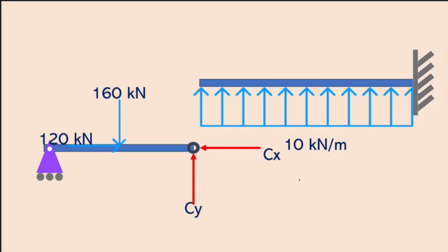And so using R is equal to 3N, diba, yung R natin will be tatlo. We have 3 is equal to 3 times the number of members, which is 1. And so we have 3 is equal to 3. And so our beam will be determinate. And so we will first cut this segment. Now we can directly solve CX saka CY just by using our equilibrium equations.